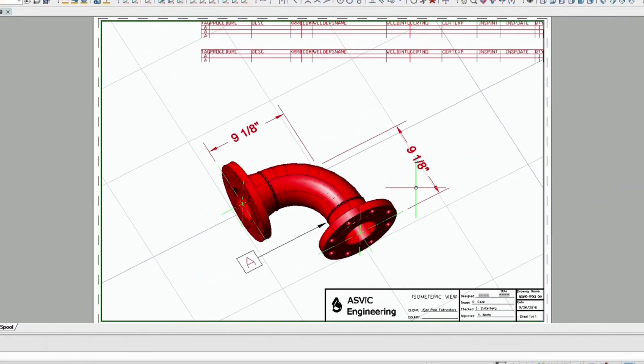Most of the first part of this video was spent setting up the general bill of materials to use for weld mapping. Let's see how to use it on a smaller sheet with a different zoom scale. Since the data for the pulldowns is contained in a separate Mech-Q file, the welding procedure numbers and welder's information will be available in all future drawings. It's now a simple matter of adding the correct data to the fields or adding new data to the pull-down menus as necessary. No setup or adjustment to the BOM table is necessary.